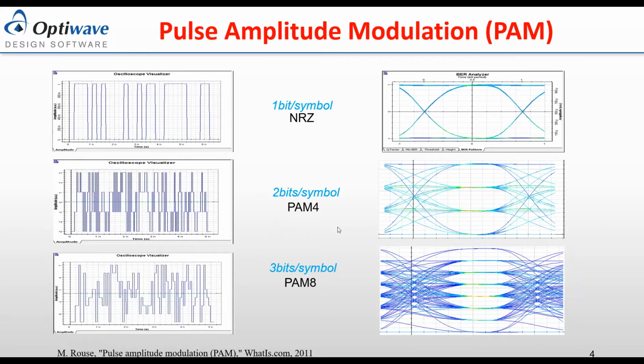On the left, we see the PAM4 signaling, where the signal will have 4 different levels. And on the right side, you see an eye that has, instead of 1 opening, 3 openings. Obviously, the signal to noise ratio is inferior compared to the NRZ eye, but it is reasonably good, it can be processed, and it has been successfully shown to work in the real world.